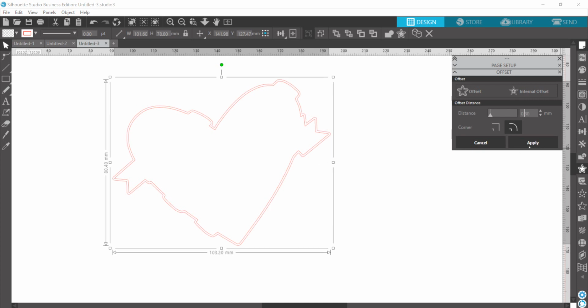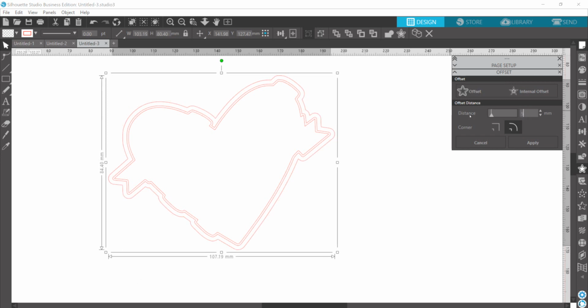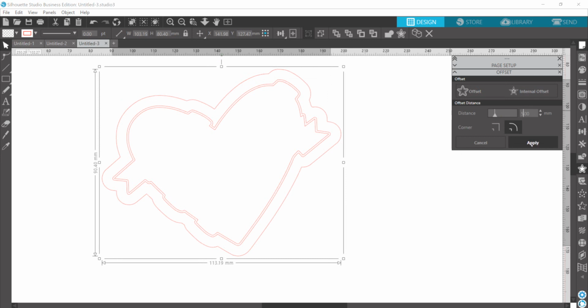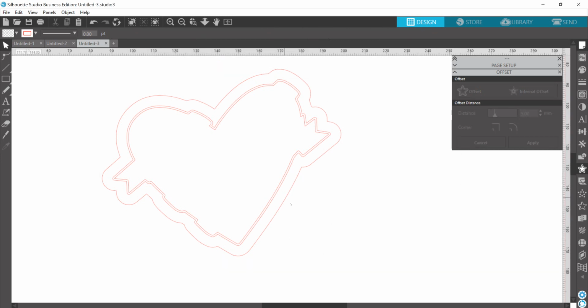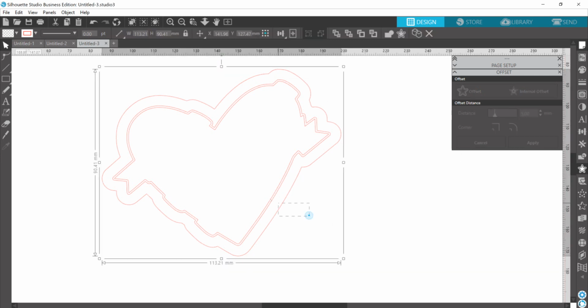You don't have to click apply. Don't do anything at this point, just leave it with the bounding box around it so that you see these lines. That's your bounding box. Go to offset again, key in the size that you want your handle, press enter, and now you have your cutter, in the simplest form.